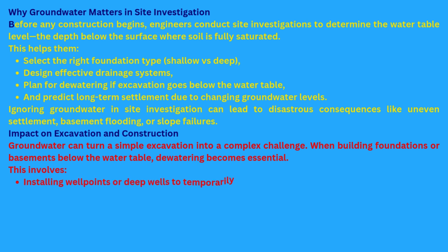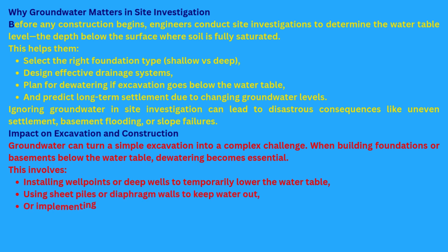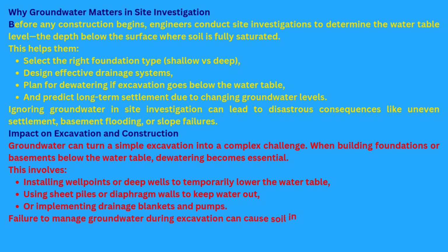This involves installing well points or deep wells to temporarily lower the water table, using sheet piles or diaphragm walls to keep water out, or implementing drainage blankets and pumps. Failure to manage groundwater during excavation can cause soil instability, machinery hazards, and delays, costing time and money.